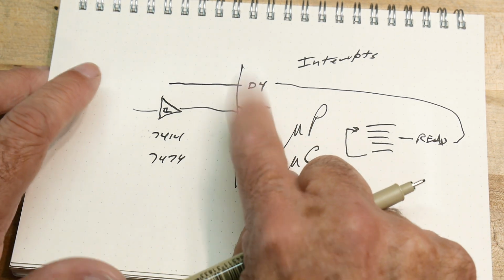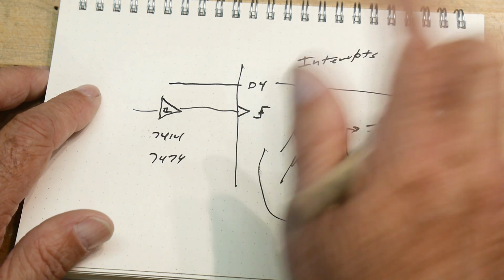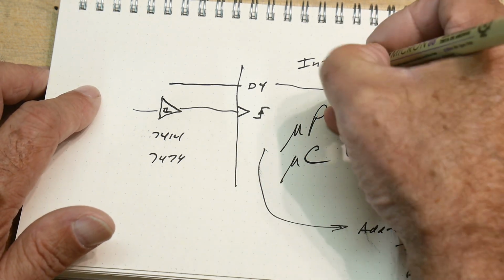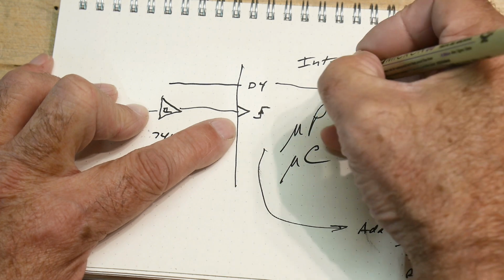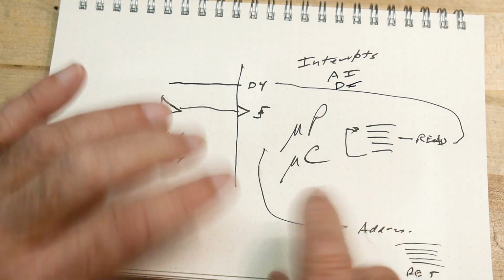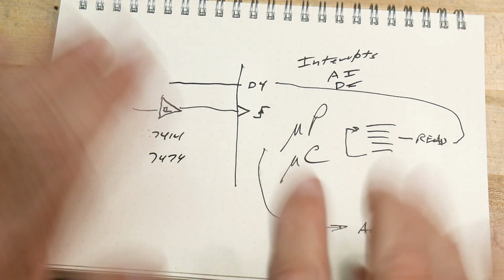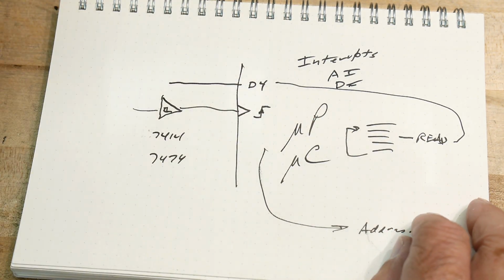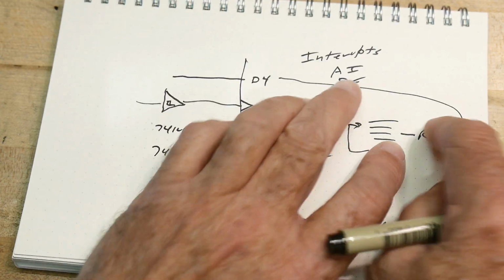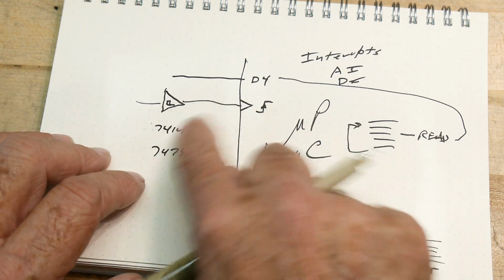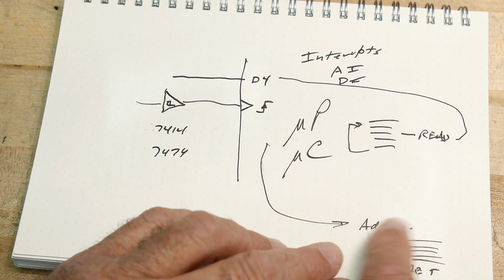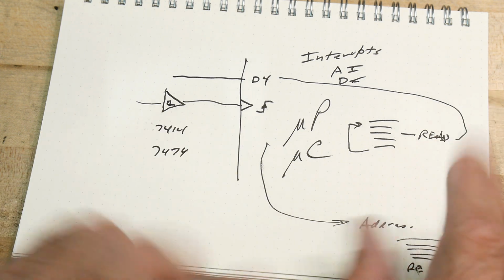You can turn these on by doing an enable interrupt, and you can turn them off by a disable interrupt. There'll be commands in the microprocessor for that. If you never want to be interrupted, it's like taking your phone off the hook. You can say disable interrupts, so you never allow this to happen, and then you can say enable interrupts.